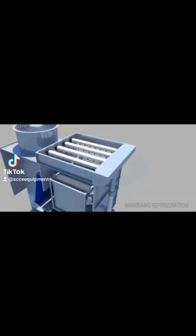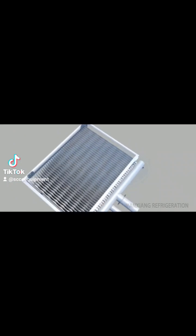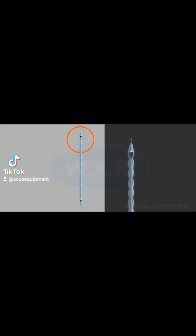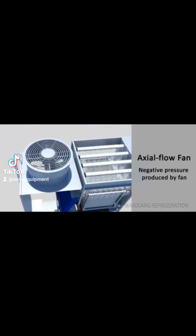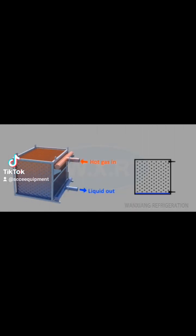Cooling water is uniformly sprayed over each plate cassette via a spraying distribution system, which results in a uniform thin film along the entire height. Hot refrigerant gas inside the cassette transfers heat to the water film. Heat transfer is enhanced in the presence of fan-induced airflow in the direction of the falling water film, and partial evaporation of water. The condensed refrigerant leaves at the bottom of each plate cassette and is collected in the lower header. This geometry results in a reduced charge.